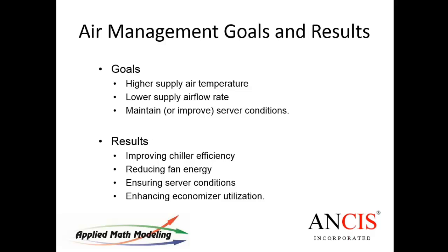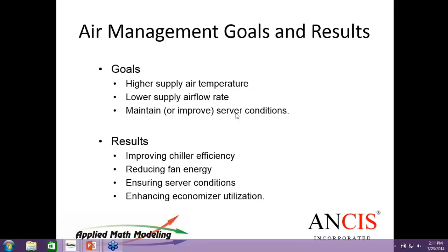And the results will be improving chiller efficiency, reducing fan energy, and ensuring server conditions. And of course, this is very important out here in California, they're building data centers with just free cooling, with airside economizers, and if you have good air management, you're increasing the utilization of an airside economizer.